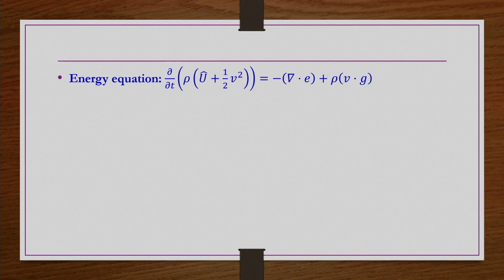Okay. Before getting the concentration profile, we try to look at the energy equation and its simplification as per the constraints of the problem. Energy equation we have derived in week number 4. So, this is what we have got, whereas this E is there in all 3 directions, x, y and z, and each E consists of contributions from conduction, convection, work done because of the pressure, viscous dissipation, etc. All those terms are included in all 3 directions, right.